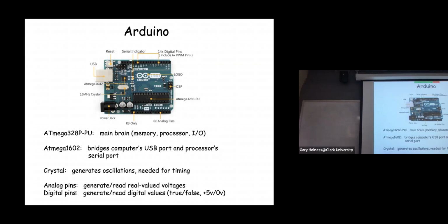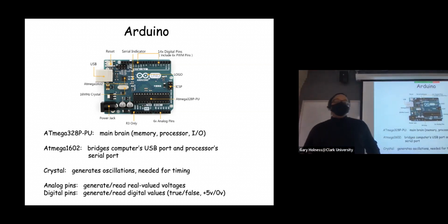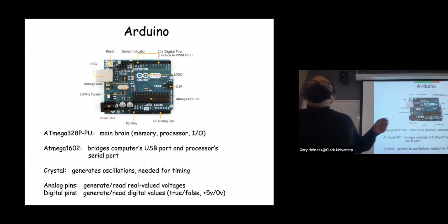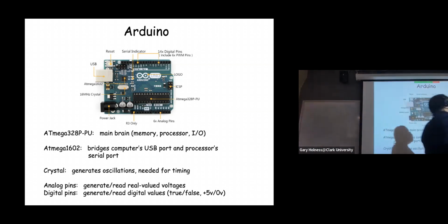So the plain vanilla Uno 3 has the main processor board, the ATmega328P. It also has a second processor, and the second processor, the 16U2, is purposed with translating or bridging between the USB protocol, it's a bus-based protocol, and the internals of the chip. Because inside this board, things are serial, but when you look at something like USB, it's address-based.